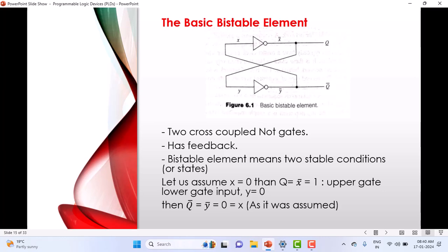Sitting at the logic level, I may say that you are giving input 0 and I am getting its complement. But how do you get that? The circuit has transistors, one NMOS and the other PMOS. It should accept logic levels. There are so many questions which will arise when you develop an inverter. Generally, when we apply 0 volts, we say the output is 5 volts, which is logic 1. The question is, what if I apply exactly 2.5 volts, the mid of logic 0 and 1? Anybody can guess what is the output of the inverter?